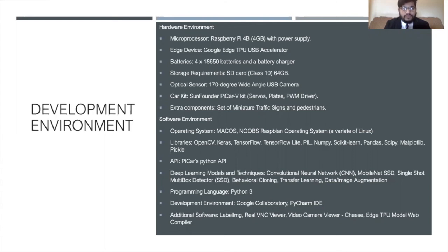I had to install a lot of software which needed to be compatible with specific versions. The specific versions are also provided in the report, in the implementation and installation sections, because some versions of OpenCV aren't compatible with TensorFlow Lite or the Edge TPU. These specific versions need to be kept in mind moving forward, because even if one library doesn't work, the whole car won't function.